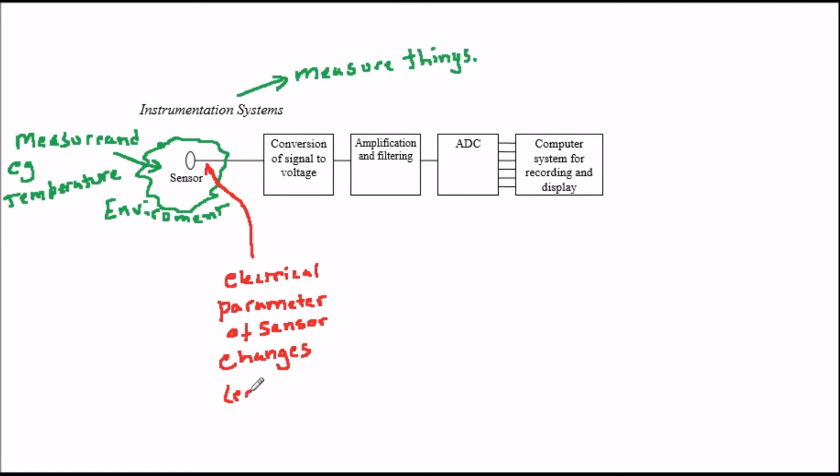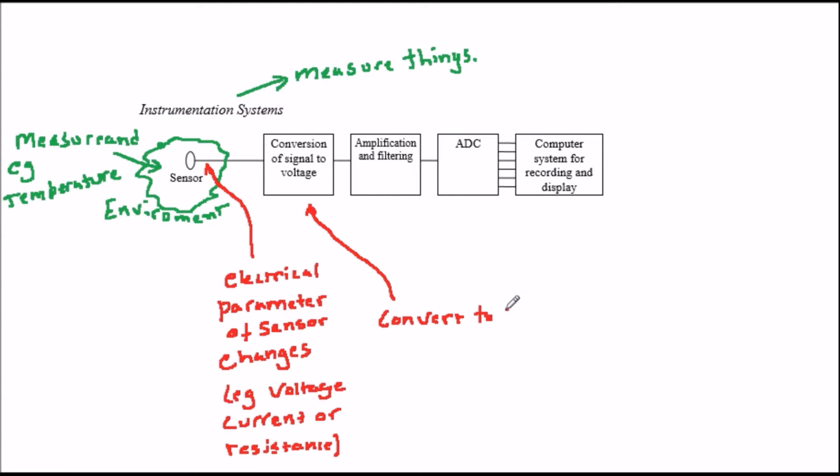Regardless of what electrical parameter changes in the sensor in response to the measurand, this change must be changed into a voltage for further processing. Voltage is generally the easiest electrical signal to handle in a circuit. This is because, unlike a flow of current, voltage doesn't heat up the circuit or dissipate power in the resistance of the wires. We'll cover circuits for conversion into a voltage later.